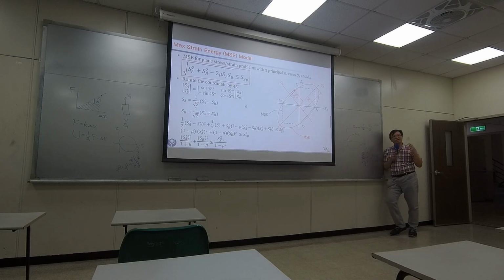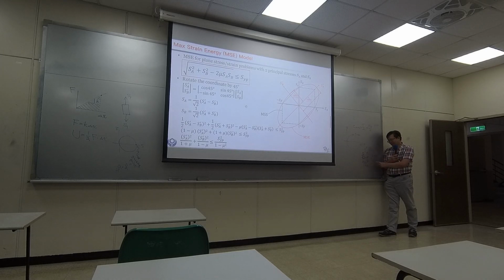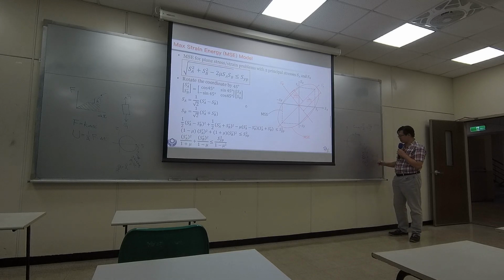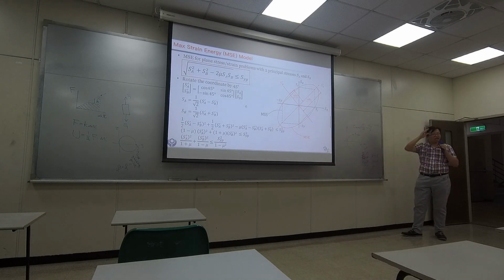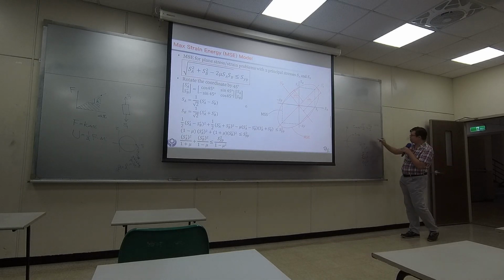So in a real world situation, Poisson ratio can never reach 0.5. It usually is a number smaller than 0.5. But usually it's not 0. If there's a material that has 0 Poisson's ratio, that means you can pull and it doesn't shrink. It would be weird.